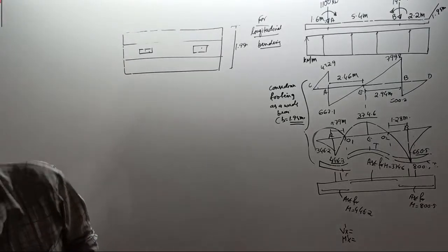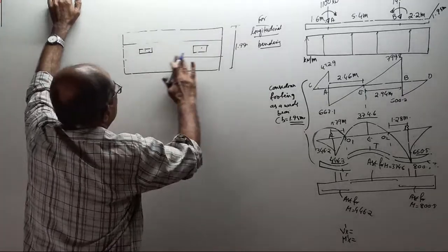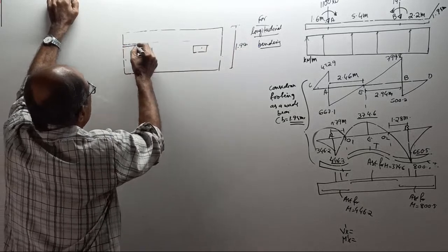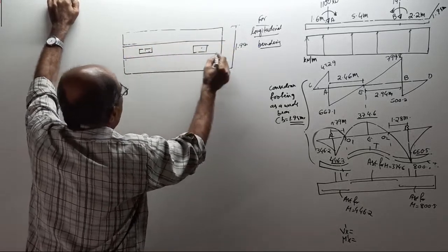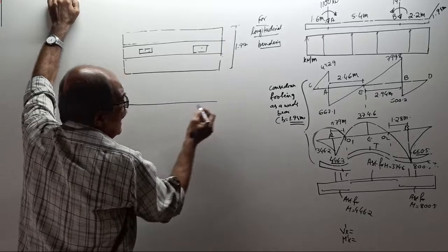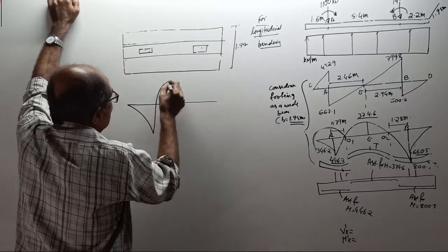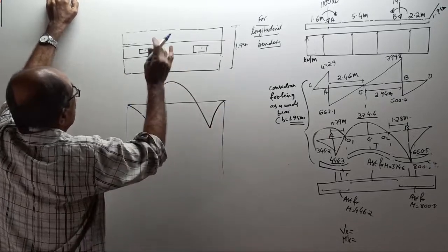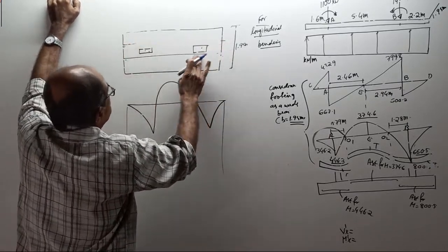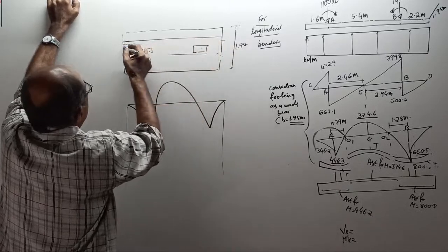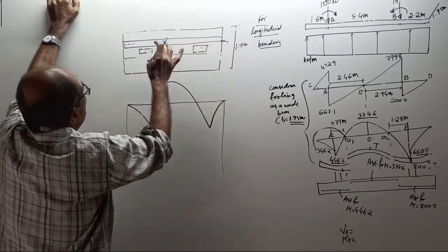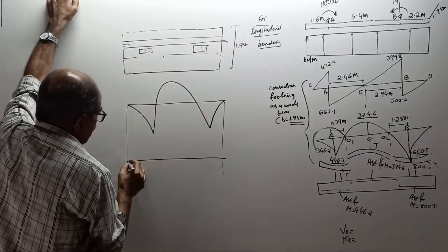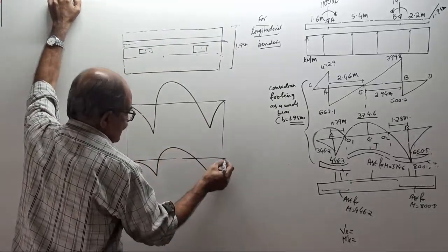It will reduce. So, I will tell you one thing now. Don't look at the width here. Suppose you take a strip here. The software will give you the bending moment diagram later. It will give you like this. Now, I will project down. Critical. Now, if I take a strip somewhere here, any width will do, even then because of the influence here, some bending will come. But the software will give you this way.